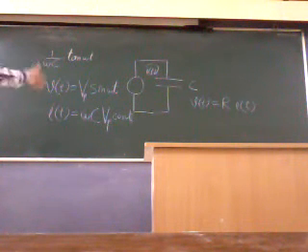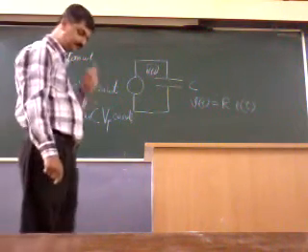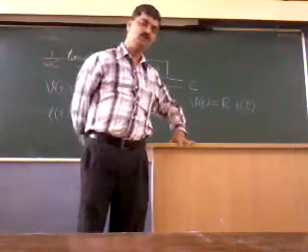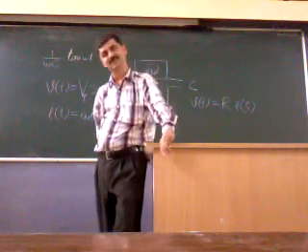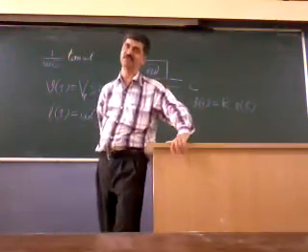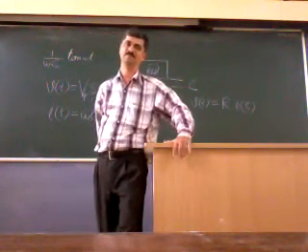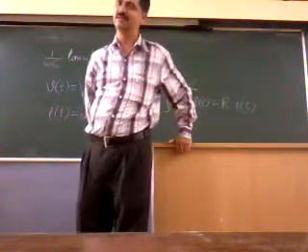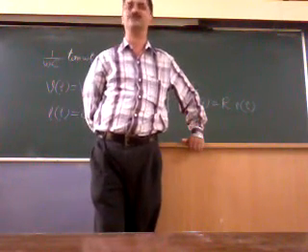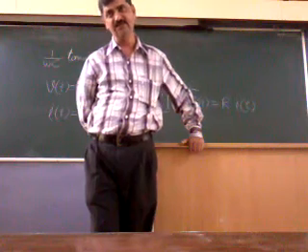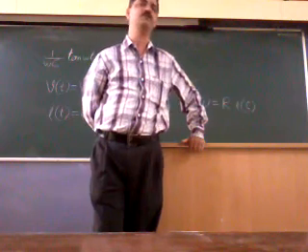Because for V(t) upon I(t), there would be a phase difference of 90 degrees. If you plot the waveforms below each other, you will find that at some points there would be zero voltage but current will flow, and at some points there will be zero current but voltage will be there. The ratio tan omega t will have its value ranging from 0 to infinity. So the instantaneous impedance, the ratio of instantaneous voltage and current, would vary largely from 0 to infinity.